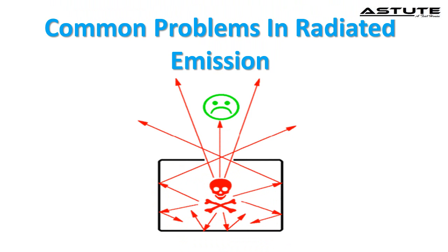Common problems in radiated emissions created by devices are given below. The common mode noise currents are the cause of high-frequency radiated emission. The most common noise source is the switching transistor. The interactions between the power supply and the power line filter. Cables act like antennas for radio noise. It is one of the top failure modes due to the high slew rate of signals on the cables.